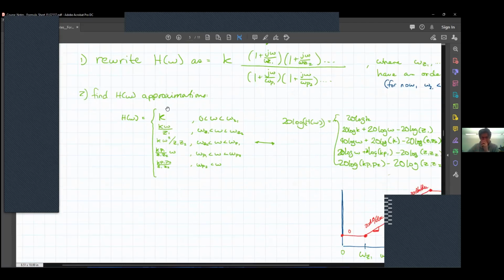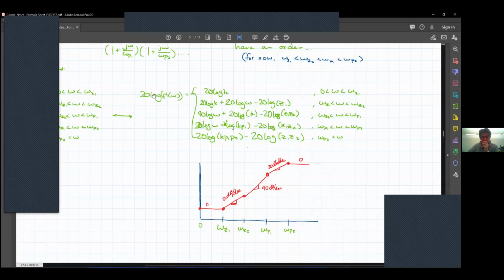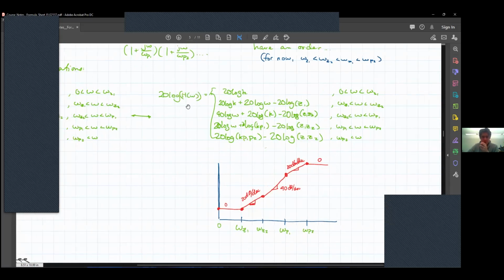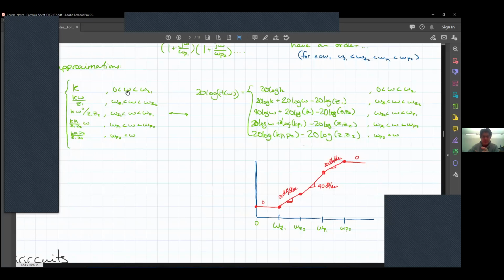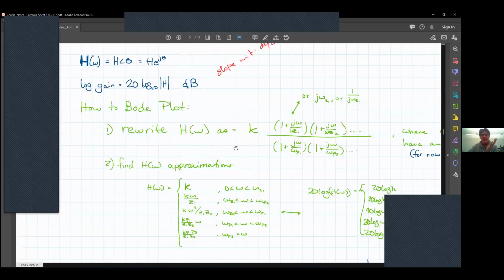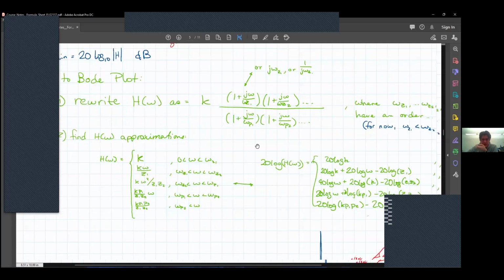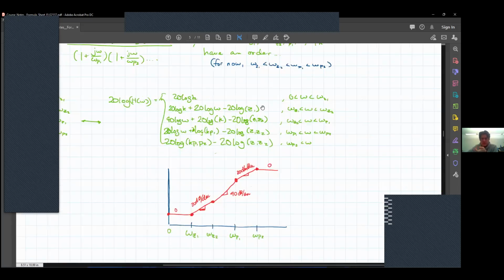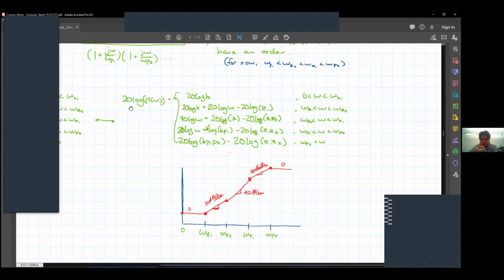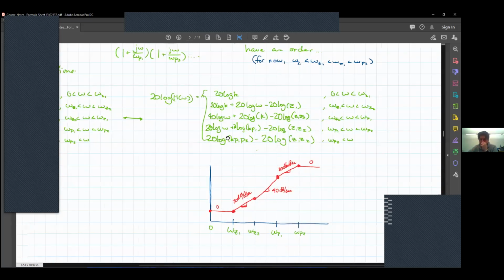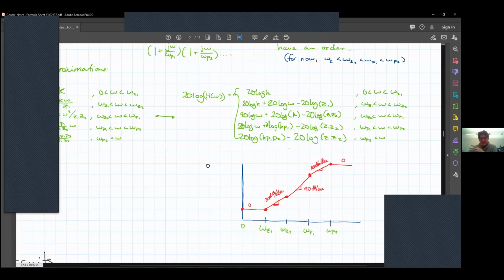So for these values, you would grab the log base 10 of their absolute value, multiply by 20, and that is your logarithmic gain. So you can see here that we have the different logarithmic gains. Note that I am using the plus and the minus form of the multiplication, since you can do that with logarithms, and it makes them a little bit easier.